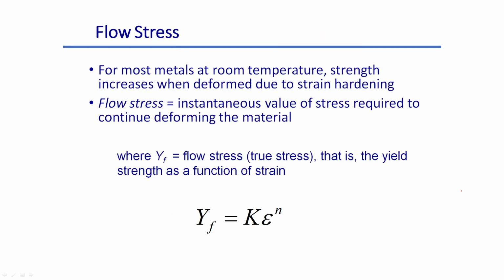Well, flow stress is what? This is the instantaneous value of the stress required to continue deforming the material. That is what flow stress is, and this is easily obtainable this way. I simply change the notation from sigma T, it becomes YF, but otherwise it is the same. So you can also write down sigma T.